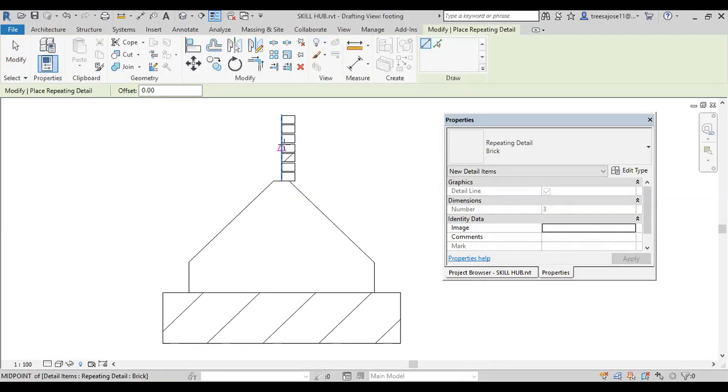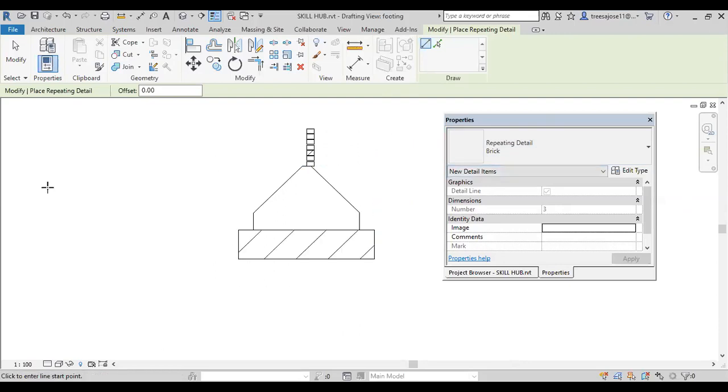This is only 2D, and this view has no connection with the model or the section or anything we created in the Revit project. Actually, this we can create as a drafting view. For detailing, you can create with the help of callout view. You have the freedom to create some detail view here also. Then if you have some details in AutoCAD, simply activate the drafting view.